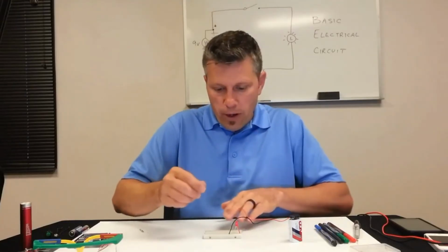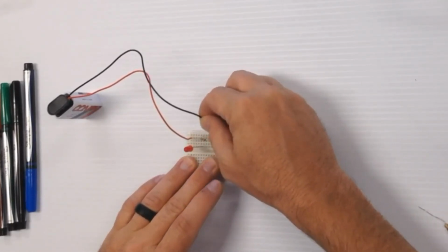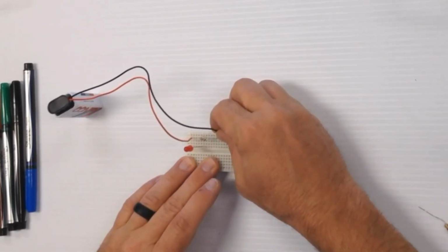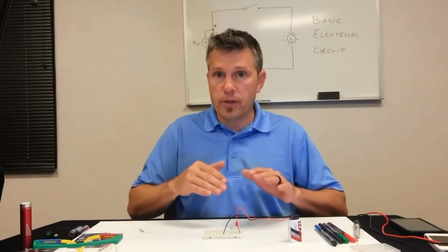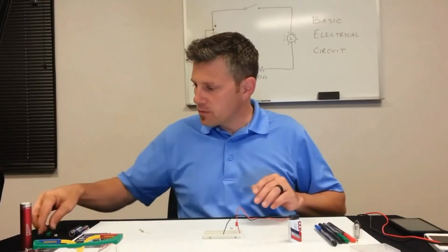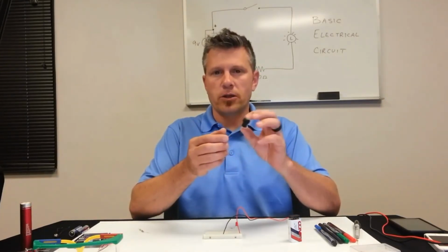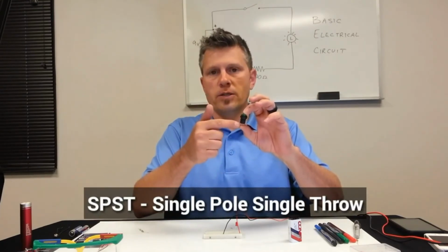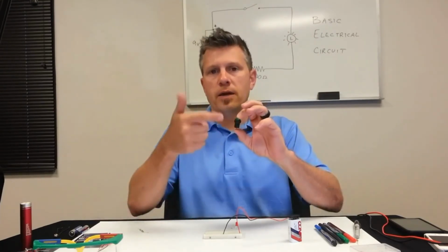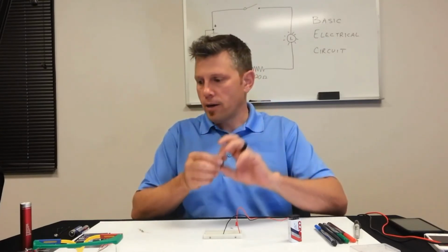With our breadboard, I'm going to take this negative power out of 10 and move it over to 15, because I want to add a switch in this circuit. I have a couple of switches here. This is an on-off switch. It's called a single pole, single throw switch. When I click it, it stays on. When I click it again, it turns off. So this switch is good for keeping something on and off.